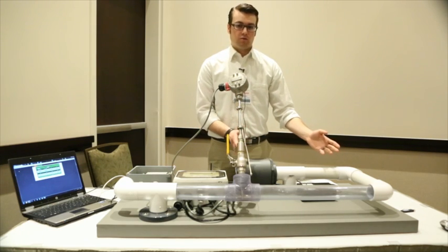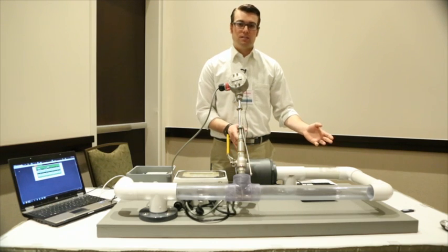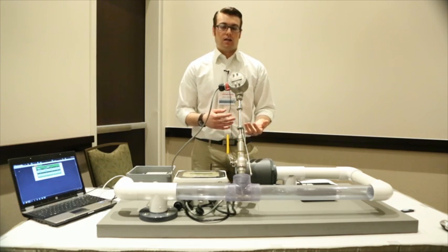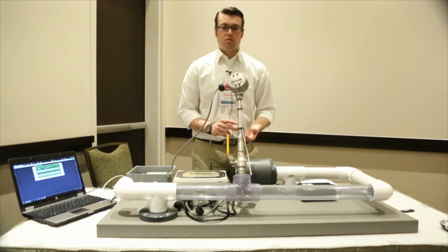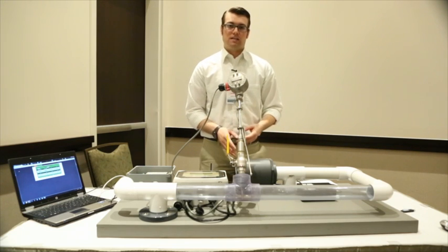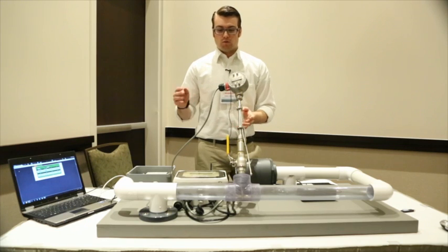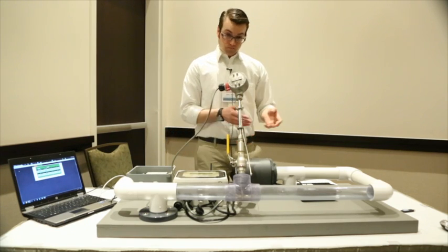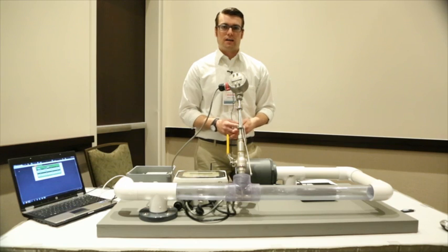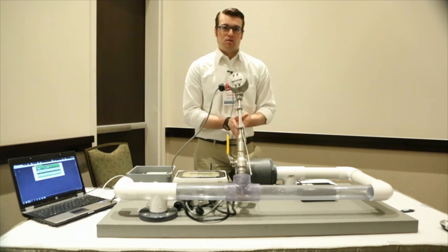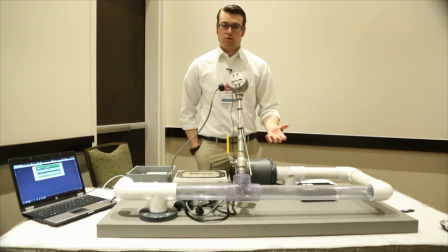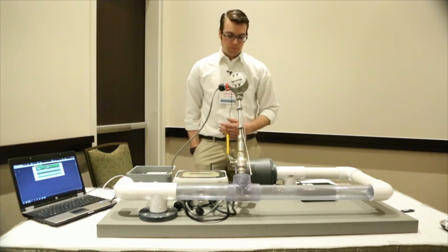First, you want to locate the flow meter roughly 10 pipe diameters after any sort of flow obstruction. That could be an elbow, it could be a T, it could be an orifice plate, it could be a valve, anything like that. You want to locate it 10 pipe diameters after that. You'll also want to locate it 5 pipe diameters before the next obstruction. The reason being, you want to make sure that the flow in the pipe is as laminar as possible. You don't want turbulent flow through your measurement area. It's going to give you an erroneous reading, and it's going to be very tough to pin down.